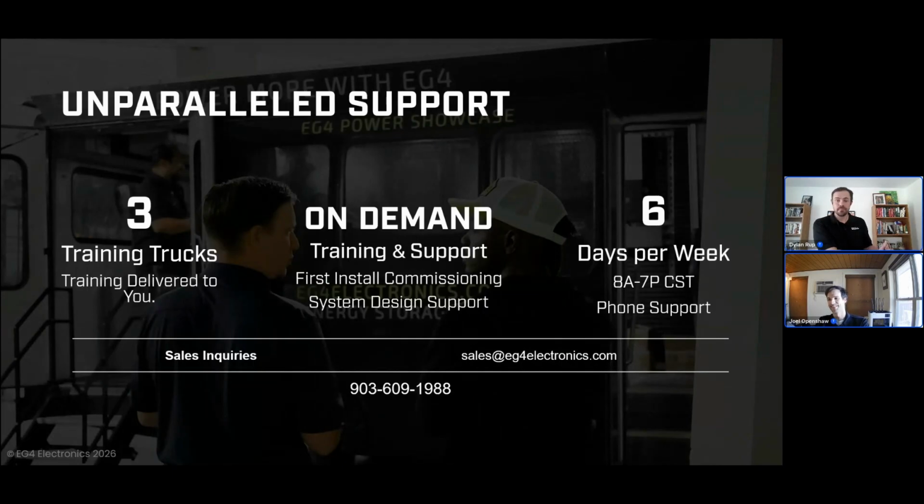Sorry, Dale. Yeah, absolutely. Thank you for that, Joel. Yeah, absolutely, guys. The implication there is from an islanding device standpoint. So the ability to safely disconnect from the grid and continue to island power to the home, you will need the EG4 inverter to have that capability and that functionality. There's some proprietary communication that happens between the two devices to ensure that happens in a safe and code compliant manner.